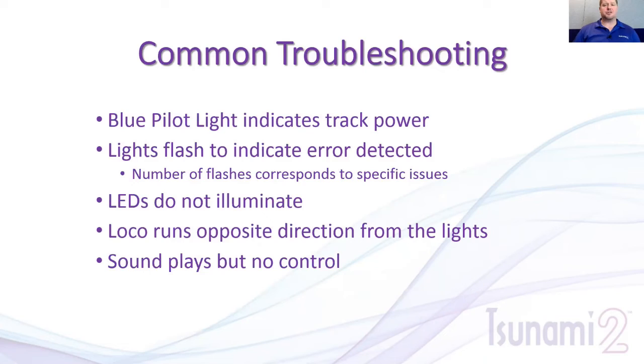Again, typically I use 1,000 ohm. They're common, they're easy to get a hold of. It's probably a little more than what's necessary, or a higher value, but it's not going to significantly dim the headlight to the point where you can't see it. You can adjust that down or even higher if you want to do a dim light.